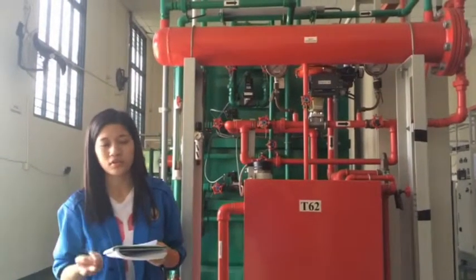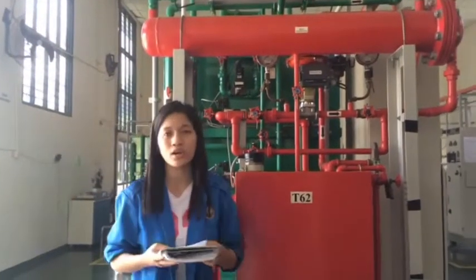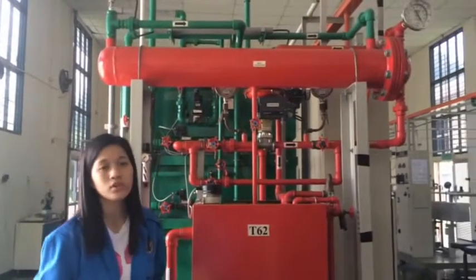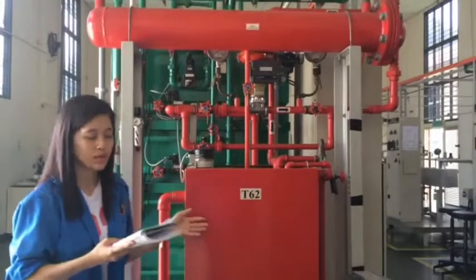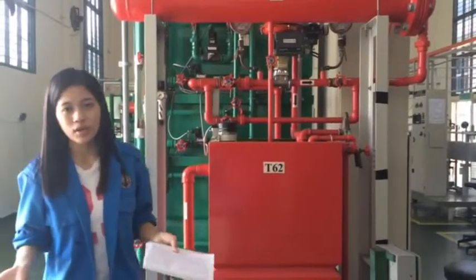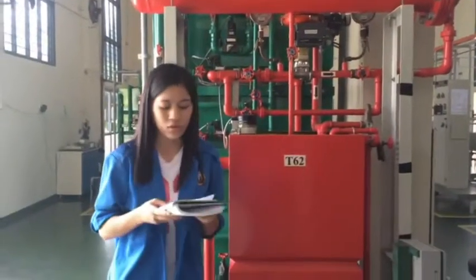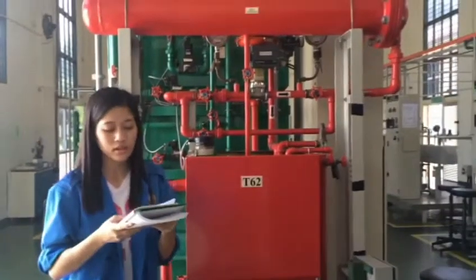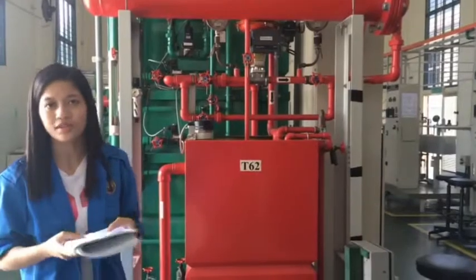Generally, we have two most common types of heat exchanger, which are shell and tube, or flat or fin. Here in this control lab, we are going to focus more on shell and tube heat exchanger. So how does it work? It works when one fluid flows through a set of metal tubes, while a second fluid passes through a sealed shell that surrounds it.